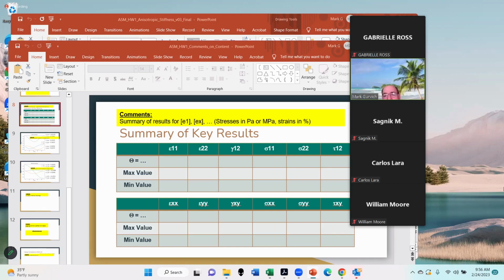When you calculate something like 0.00535, I need to mentally recalculate how much it is. But percentage is a very convenient way to estimate strains, because we know approximately between 1 and 2% we are in a bad situation, close to failure.